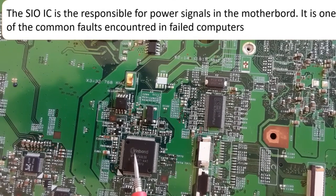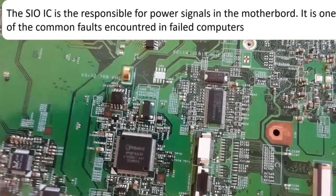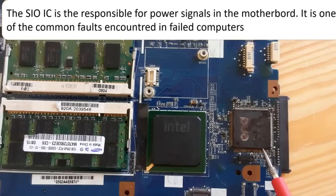Here we have another SIO, Winbond. As you can see, this is a Winbond IO. Here we have this triangle. The big triangle means here we have pin number 1, okay? And this is the direction of reading, as you can see. Okay, the same working principle. It's pretty easy with the hardware of laptop motherboards, and I show you many motherboards in order to master the hardware of the motherboards.